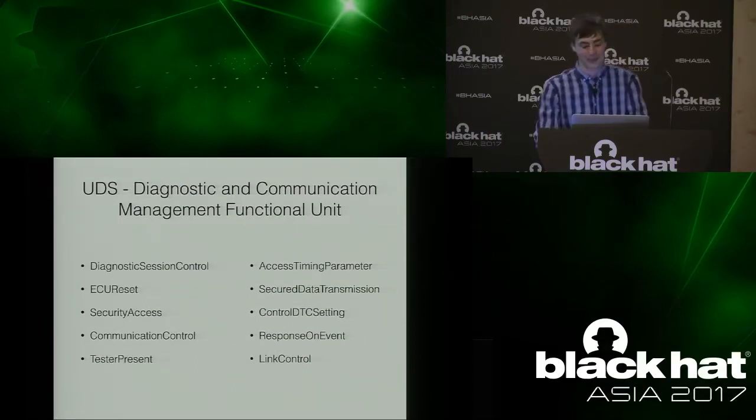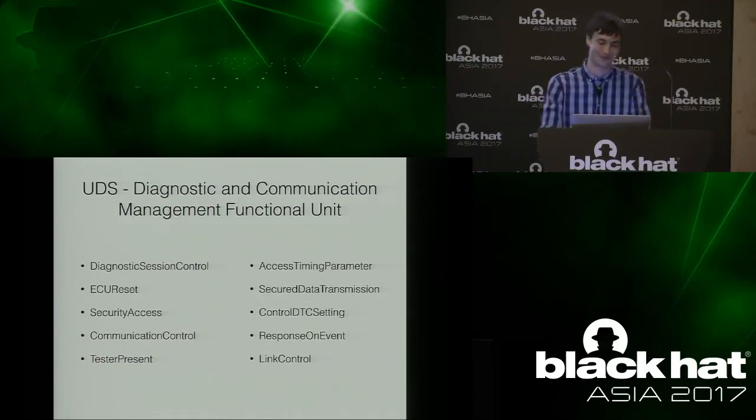Response on event is something that allows you to set up some special events and then when they occur get a response back. I've never seen it used in practice in any tools I've used. And link control lets you change the baud rate. That's not interesting unless you want to do a denial of service attack. Potentially you can change the bit rate that something's communicating on and crash the whole bus, but that's just sort of fun.